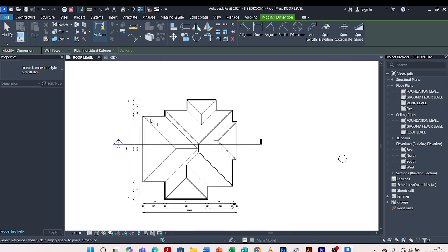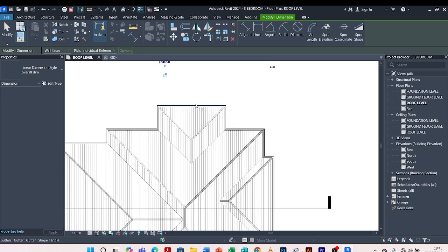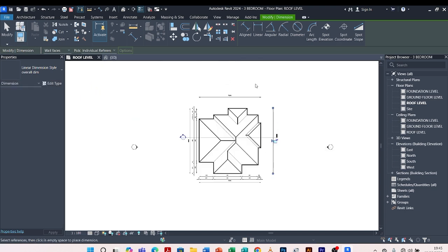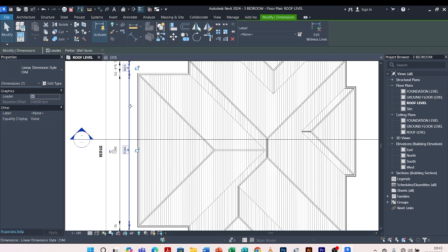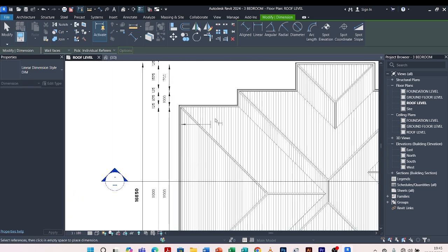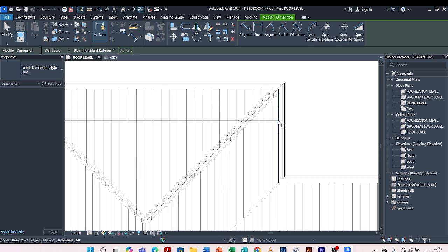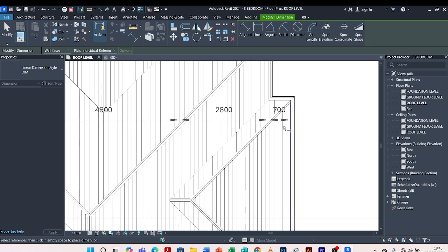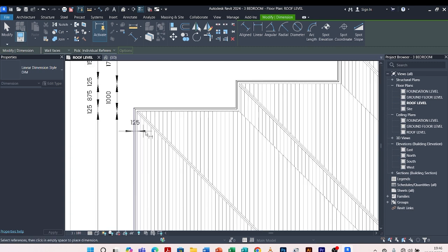I can have this on this other elevation at once, the overall one, then also this other elevation side. So I have to create similar for this first one we are using. I'll click on this dimension line, create similar, then mark off the roof edges. The next one is for the gutters.